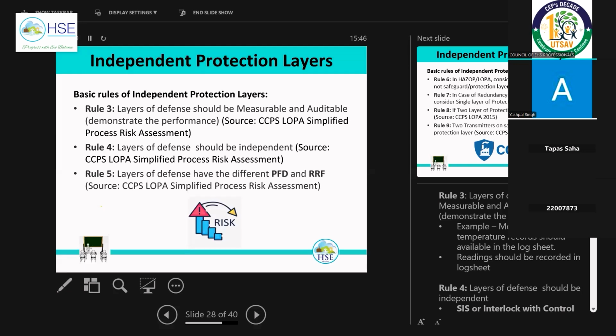Because of more flow of raw material, the temperature is increasing. In that case, we have the high pressure and high temperature alarm, and we have the control valve steam supply stop because of high temperature and high pressure. Similarly, the flow closes because of high temperature, high pressure. Suppose we say our first control is high temperature and high pressure, close the steam supply valve.